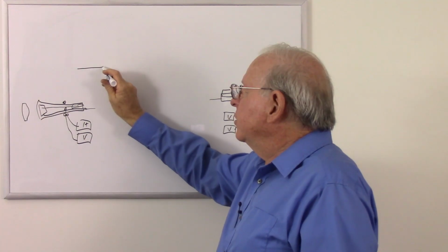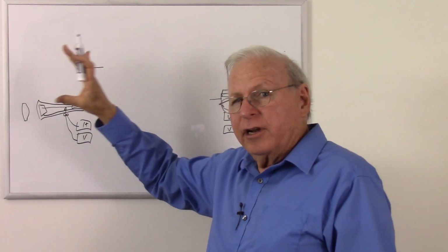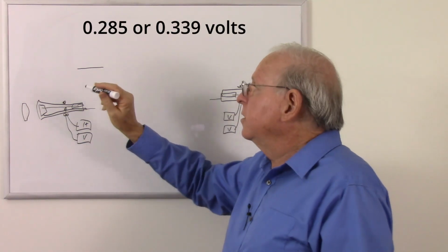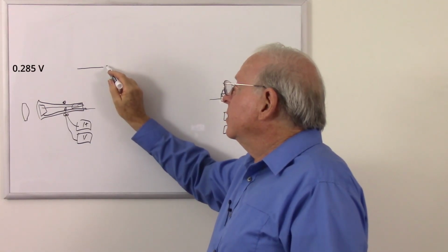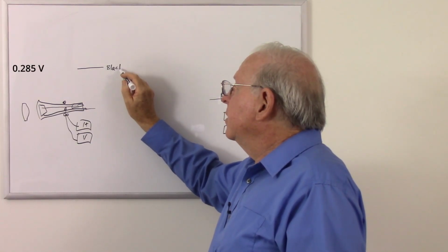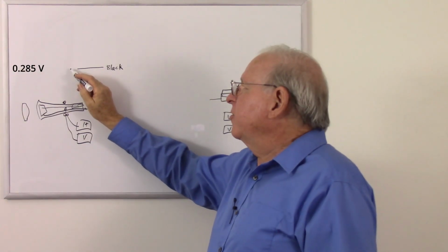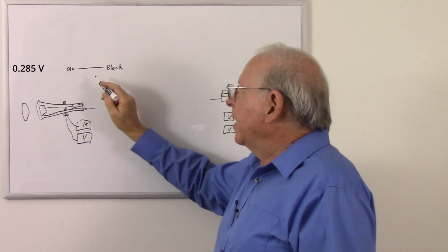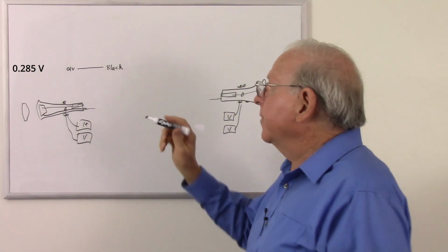a certain voltage, whatever it is. I don't know what it is at this point. It's going to be pretty low voltage, maybe even lower than a single volt. But somewhere is going to be what's called the black level. That's not going to be our lowest voltage. That's going to be something above it. Let's say that's 0.1 volts is black. So if we go below that, it's blacker than black, when there's a use for that.